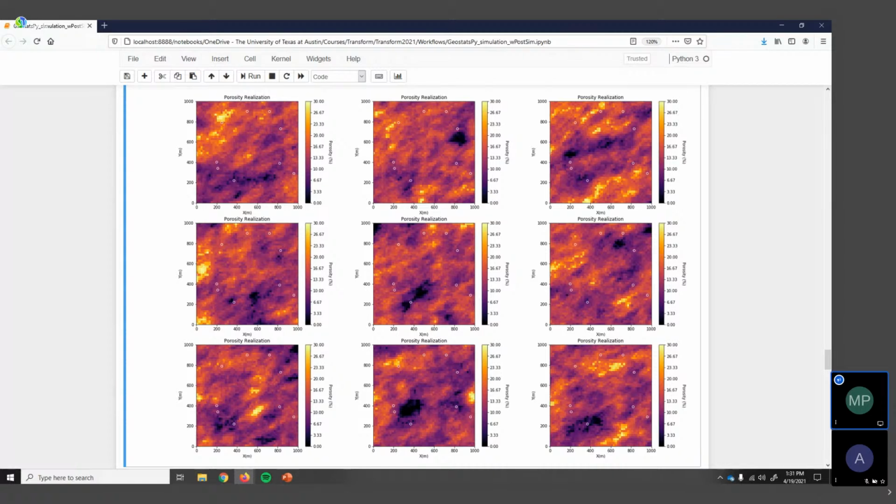We have realizations. The azimuth is 0, 6, 0 is the major direction. We have locations where we see low values all the way out to here. We have locations where they come out to here. We can see that this is informing a local low, but the stochasticity, the uncertainty away from the data, is still quite high given the spatial continuity model. And we can have cases where it's low like that, cases like this. We're seeing the differences between the realizations.